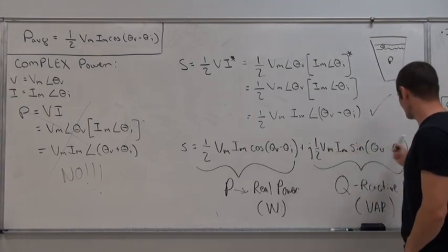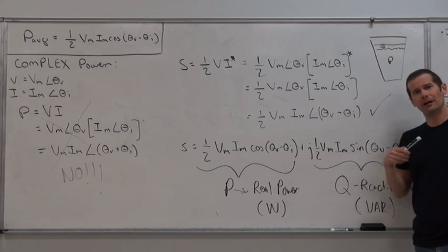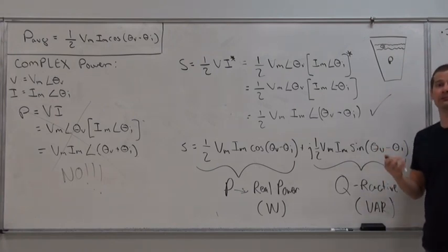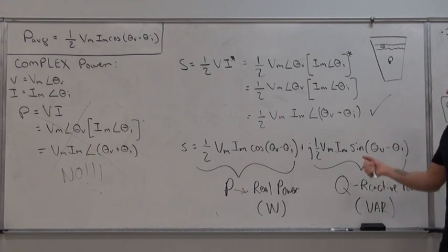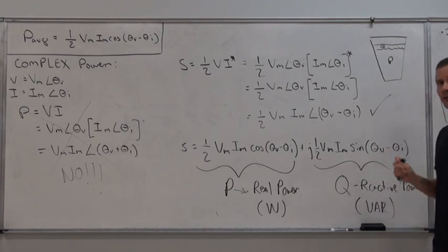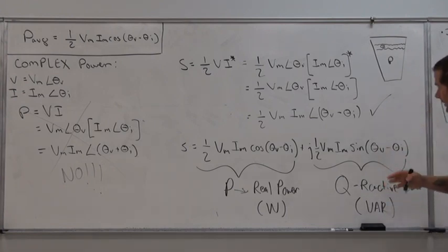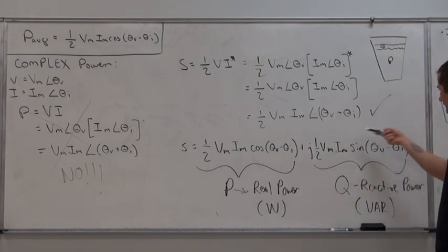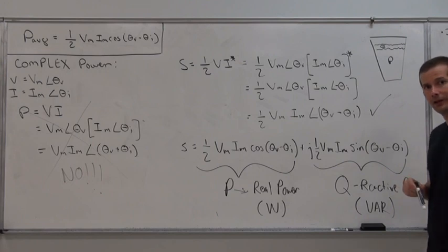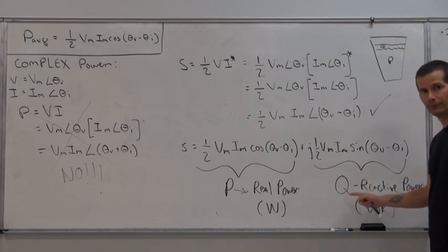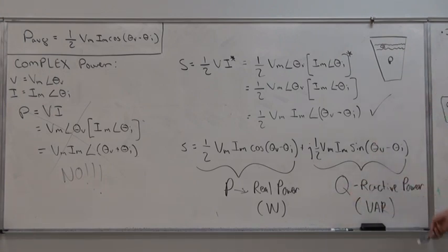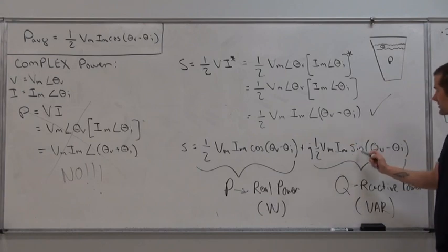Now, what's this over here? Well, by the natural notion of having complex impedances for capacitors and inductors, just by the use of inductors and capacitors within any electrical system, when we're utilizing phasor arithmetic, we're also going to come up with this portion of the complex power that we have to deal with, which we call reactive power, or Q. And by Euler's identity, we get 1/2 Vm Im sine(theta v minus theta I).